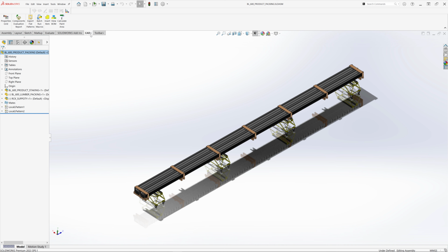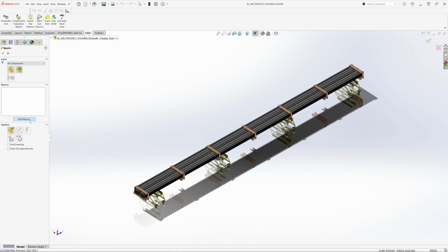But there is also another great feature of Macro Plus, as it not only can be run within the part of Toolbar Plus, but can also be run in the batch mode in Batch Plus integrated into Assembly, Batch Plus standalone, and Batch Plus for SOLIDWORKS PDM. And let me show you that in action. As a part of this demonstration, I will show how to produce a single zip file of PDF and DWG files from all drawings used by all components in this assembly.